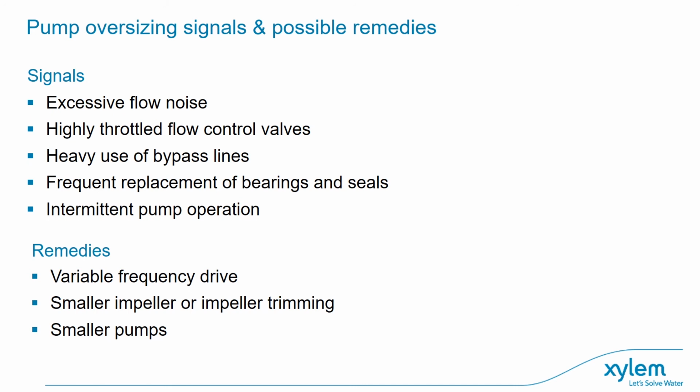When there is an oversized system, there are a lot of signs which can witness that. Correcting the oversizing can really result in a cost-effective procedure. Pipe vibration can accelerate system wear and also wear the mechanical joints of the piping. Excessive flow noise is one of the main signals, and is typically the one to which operators get used. You think you have a very, let's say, noisy system, and get used to the sound itself of it.